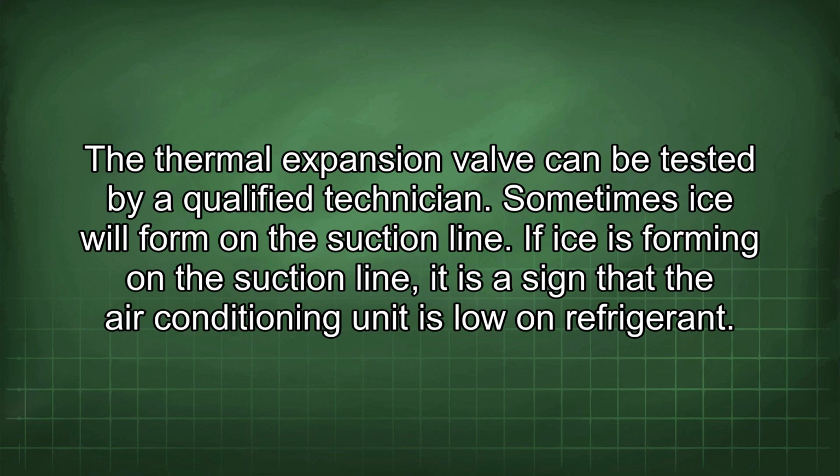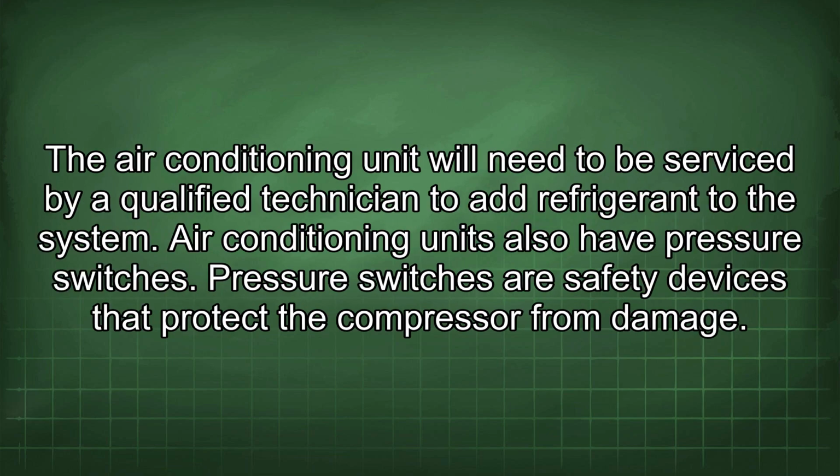Sometimes ice will form on the suction line. If ice is forming on the suction line, it is a sign that the air conditioning unit is low on refrigerant. The air conditioning unit will need to be serviced by a qualified technician to add refrigerant to the system.